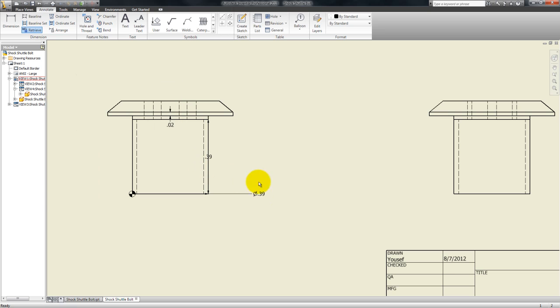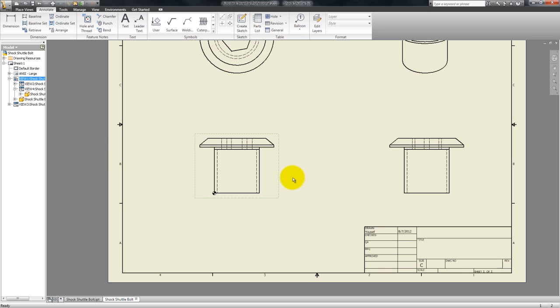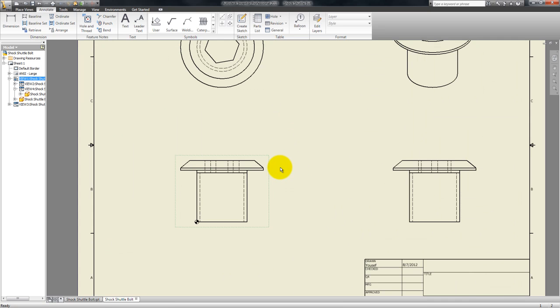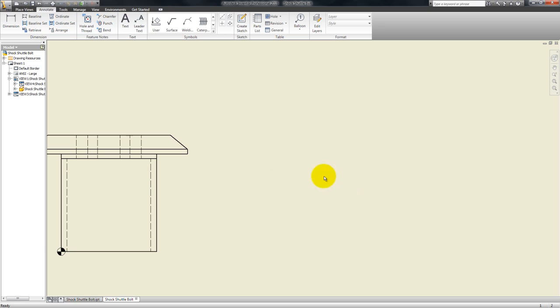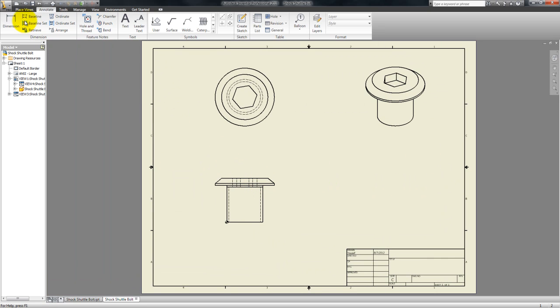But you're not going to really use this often because it places the dimensions on the drawing, on the solids. It's not very useful. It just makes everything cluttered, and I find it's actually easier just to dimension everything from scratch yourself. This view is really redundant. We don't need that because we've already got a front view and it's symmetrical. So anyways, just how I would dimension this quickly. I'd make sure I don't repeat any dimensions. You just label each feature on the side where it's most descriptive. So for example, we'll do the height here.